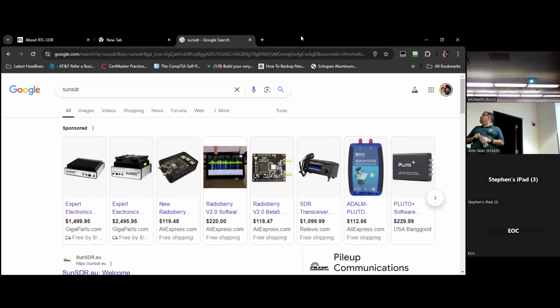It was weird because there were no obvious antennas. The only thing the guy had was a Dish Network dish. I can't say that it wasn't a legit Dish Network dish, but it was also causing spurs on the same frequency. It really surprised me how many things lit up when I fired up the Kraken on our two frequencies on 2 meters, the input and the output.